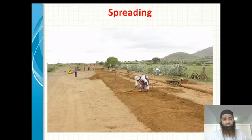Next you can see in this figure how spreading is done. The mud is spread in an even manner, so that the road forms in a very even manner. There shouldn't be ups and downs, because this spreading forms the layer which is lowest to the soil. So this is the subgrade soil, and this is the sub-base course. This acts as a sub-base course which is placed over the subgrade soil. Subgrade soil means that one which is your earth, the last part. Over that, this is spread, this is the base course.